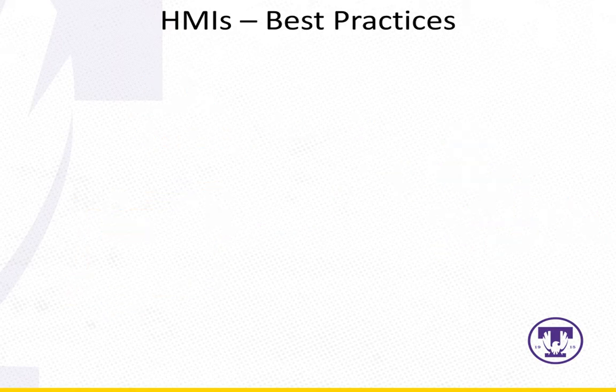So now let's turn our attention towards some best practices for when you're developing HMI applications. First of all, it's not best to always have to reinvent the wheel. So if you're developing an application that has similarities to an application you've developed previously, you're best to start off with sort of a starter file rather than having to go back to square zero every time, because there's lots of settings and lots of little things that you have to remember to do when you're creating a new HMI application. So in general, it's best to have some sort of starter application where all that's set and you always work from there as your square zero.